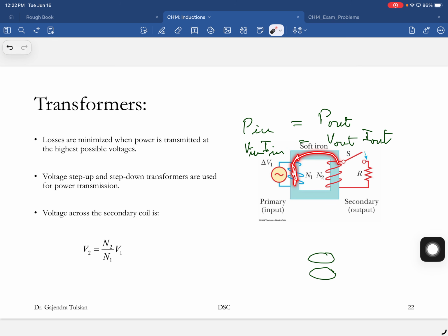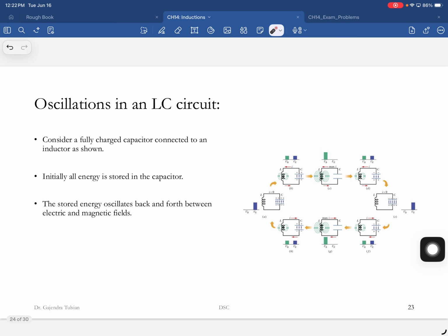This is using magnetic materials you're connecting, okay? So if this was not magnetic, then that wouldn't couple. So it has to be a soft magnet. Its magnetization is easily changed directions. You'll learn about hysteresis. If it's not easily changed, then a lot of that energy gets converted to heat. So it has to be easily magnetizable, and that's what a soft iron is.